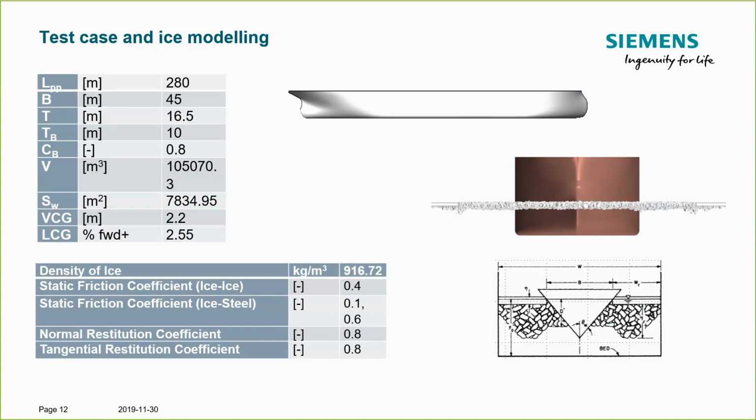So basically our solution domain will consist of a block that is representative and a finite anticipation of our ocean. And then there will be two ice sheets at a defined thickness that constrain the flow laterally across this thickness. In between and underneath, you can see the ice particles, represented by DEM particles in Star-CCM+, conglomerated.